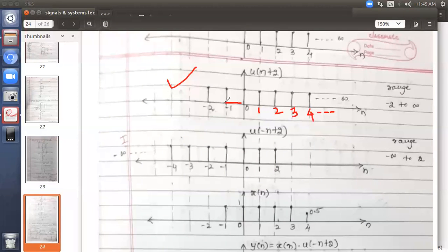Now, if you observe, this is the negative side. If you change the sign of this time n, it's already minus. Put one more negative sign before it. It will become +2 and +1. So these two samples, which are actually at -2 and -1, will now be at 1 and 2. Because of time reversal, we are taking the mirror image. Whatever time value you have, just put a negative sign before it. Minus into minus becomes plus.